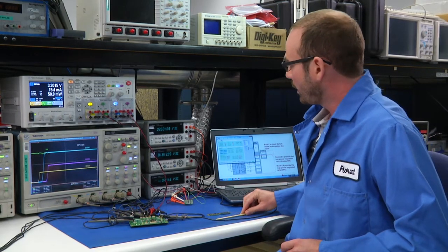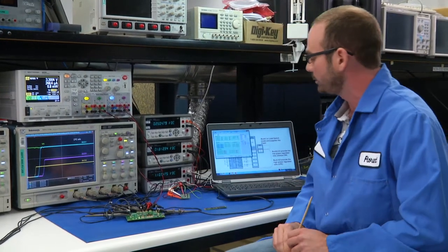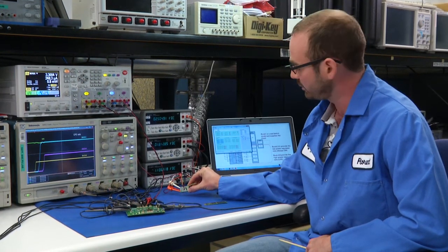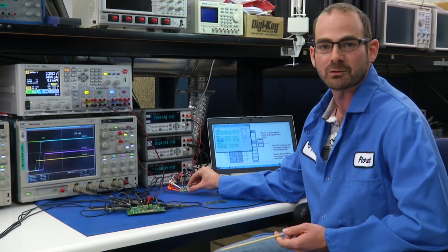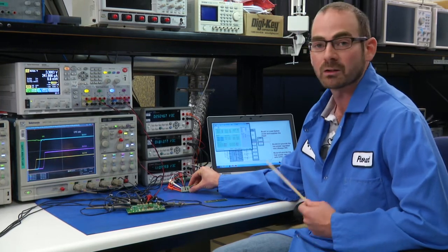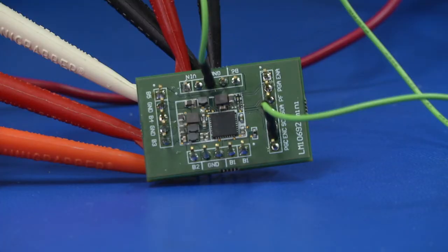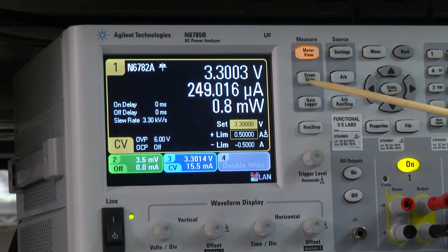Now, I want to show you the low operating current of this device in idle mode. So for this, I will be using the mini evaluation module, which is here, which has none of the LED voltage sensing bridges on the evaluation module that are taking additional current. So we can see the current consumption of this solution. So you can see here the enable CPE line has been pulled low and only the always on rail are running. And you can see in this power analyzer here, the current consumption of this device is about 250 microamps.